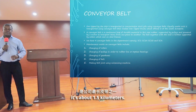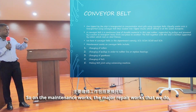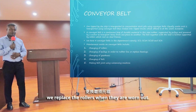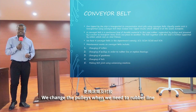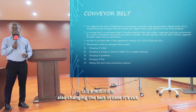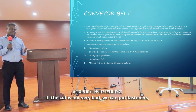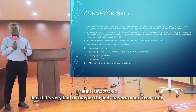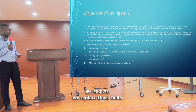It's about 1.5 kilometers. On the maintenance works, the major repair works that we do, we replace the rollers when they are worn out. We change the pulleys when we need to rubber line or change bearings. We're also changing the gearboxes. We're also changing the belt in case it's cut. If the cut is not very bad, we can put fasteners, but if it's very bad or the belt has worn out over time, we replace those belts.